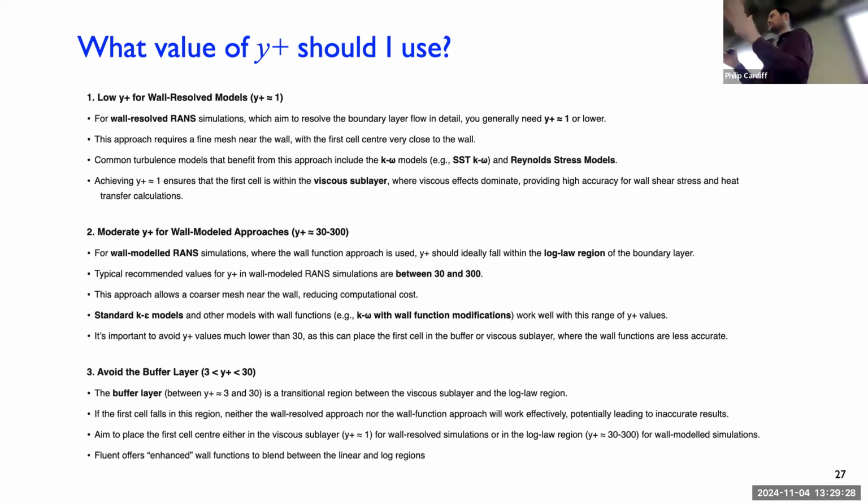And then based on that, you will check what the values are. And if most of the car is like 10,000, it's like, okay, we're nowhere near even the boundary layer at all, the turbulent boundary layer. Then you resolve it. If all the y pluses are 1 to 6, it's like, okay, we've got way too many cells. We're over resolving it. And so by the nature of it, you'll have to iterate. But imagine you go into a company that designs cars, they'll have experience running these. They will know that for traveling at motorway speeds, the first cell needs to be a millimeter thick or something like that. So they'll already know a rule of thumb and they'll just verify that's appropriate afterwards.